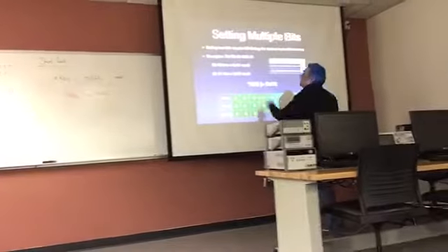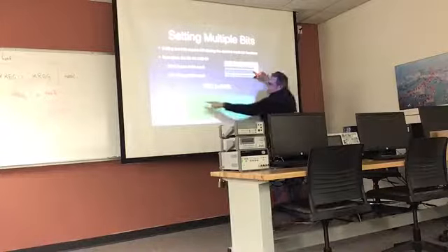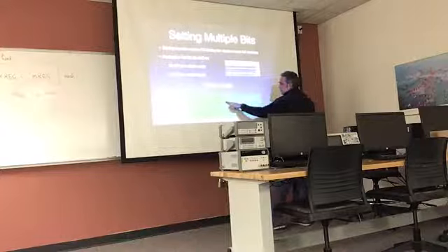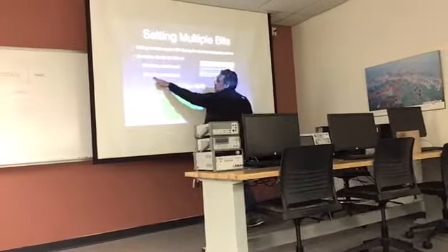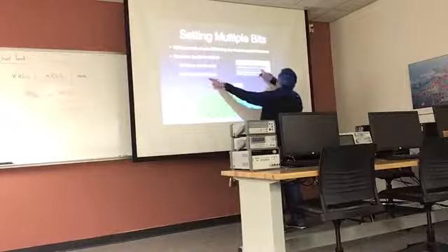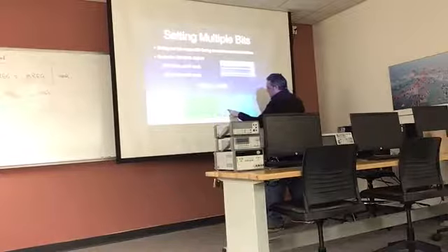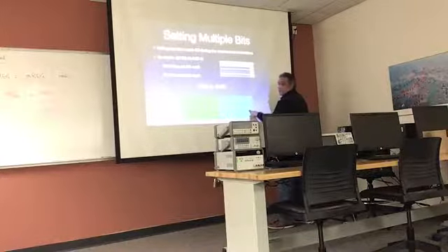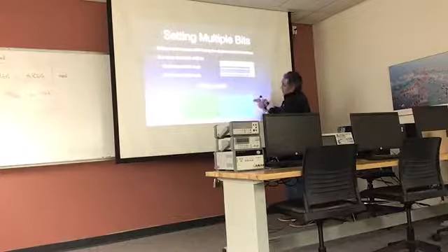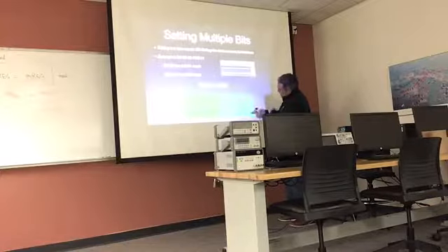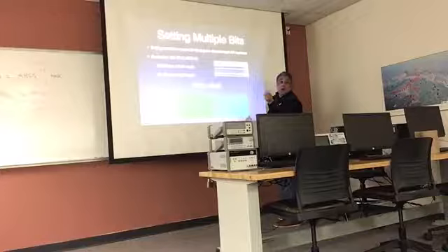So here we go. Location 0, according to my table, is hex 1, which is written right here. Right? Location 1, bit 1, has a mask of 2. That's my table 2. Location 1 has a mask of 2. That's this number right here. And if you OR gate these 2, you get this and that, right? You OR gate these 2 to create one and the other.